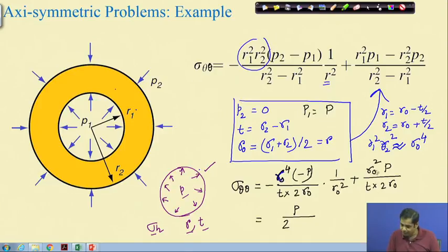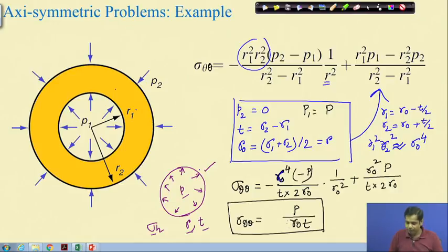then we have R0 into T, sigma theta theta. So, there will be no T2 term. This is the final expression, R0 into T. So, you recall in strength of material, or in your first year mechanics, for a thin wall pressure vessel you obtain the expression as this, and we just now saw this expression can be obtained from this expression as a special case.